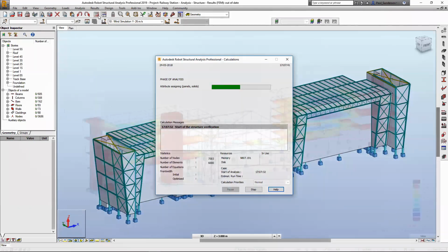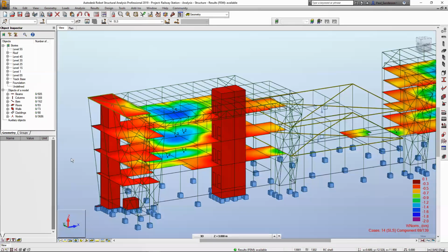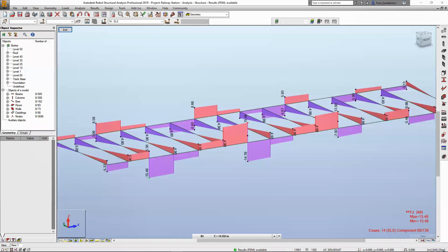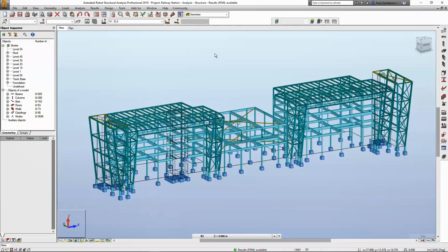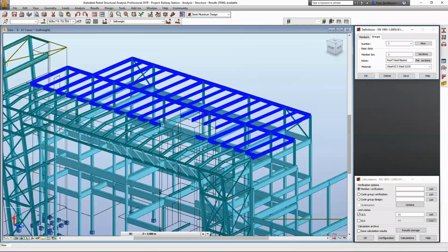And you can easily run the overall structural analysis of the project and start looking at which kind of loads you're dealing with, what bending moment diagrams you are getting in terms of the loads, and the shear forces. This also integrates the dynamic loads, where, as I said, you can easily specify the code of practice that you want to perform those analyses with. Then you are able to generate the results.